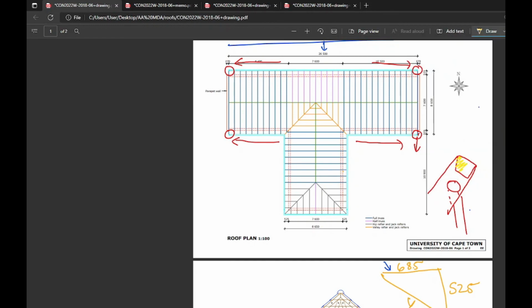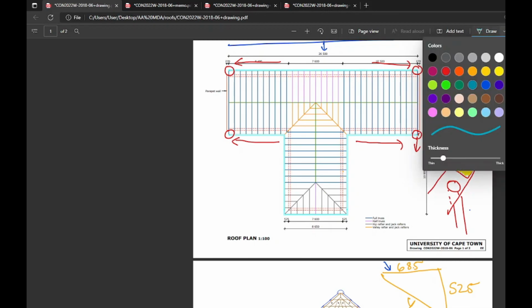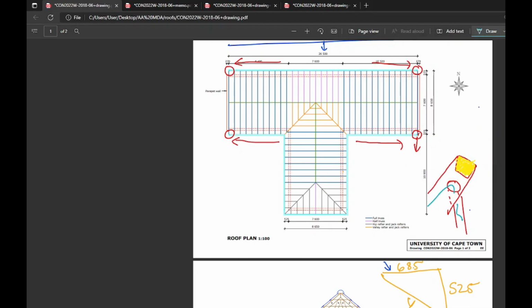Otherwise, how is your water going to go down your downpipe? You kind of just launch the water off the end, and sure, some will go down, but I think the majority in heavy rains will just rush straight past and hit the end. Thankfully, because we have the stopped end, the water is pulled back and goes out the downpipe. So it's not so clear, in my opinion, that a stopped end should go there.